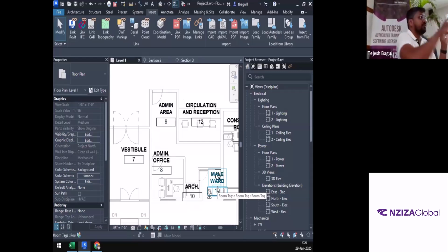But we need to make sure we understand the heat load caused due to the people as well as the equipment as well as the lighting in that room. So Lawrence, to answer your question, there will be no wall or window assigned in this area. It will be only the internal loads, people load, lighting load, equipment load that we will consider for this area, and based on that we will have our HVAC system sized.